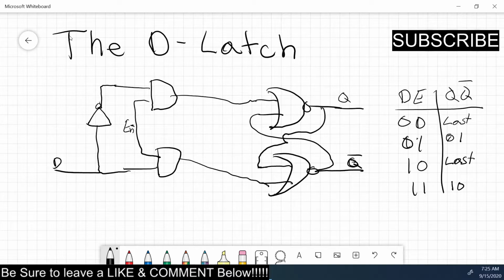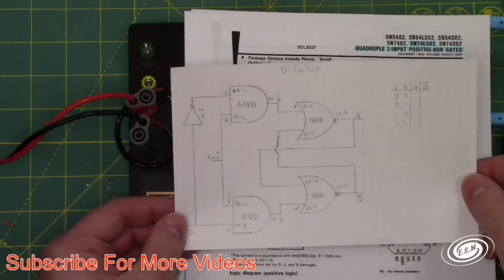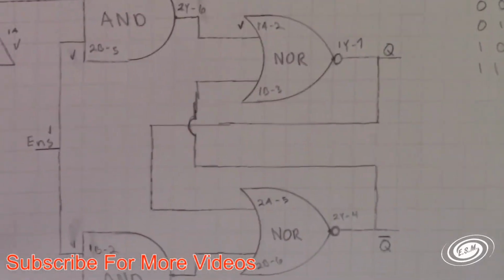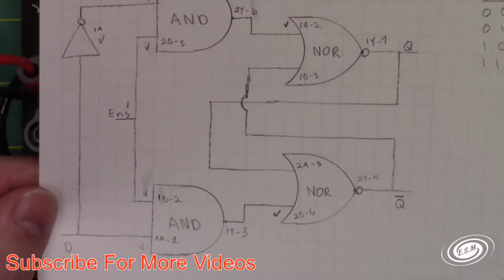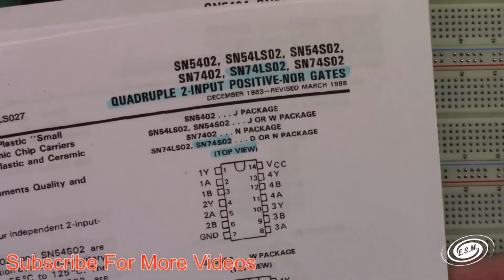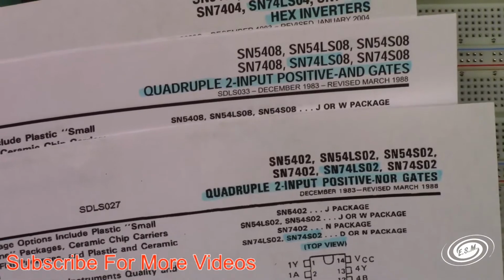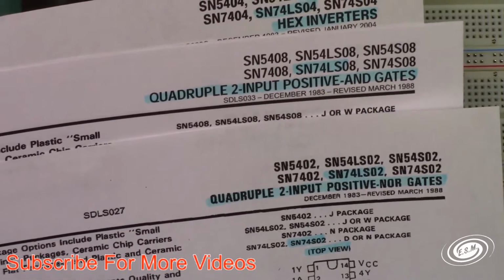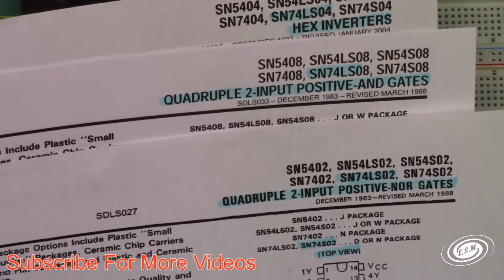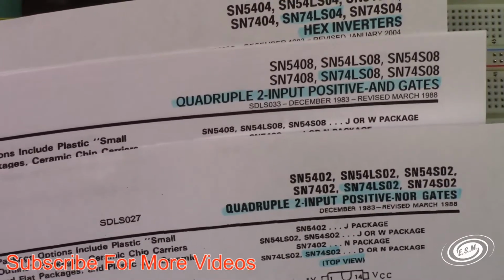So let's go to the overhead view and take a look at this here. Here is my nice and neat drawing of the circuit and how I hooked it up. Let me go in a little bit here so we can see this. It is in pencil in case I make a mistake. So I'm using 3 logic gates. I'm using a 74LS02, 74LS08, and a 04. That's a hex inverter, 2 positive AND gates, and then a quad NOR gate, 2 input. So I could have turned one of the NOR gates into an inverter, but it would have been messy on the breadboard, so I used the inverter chip.